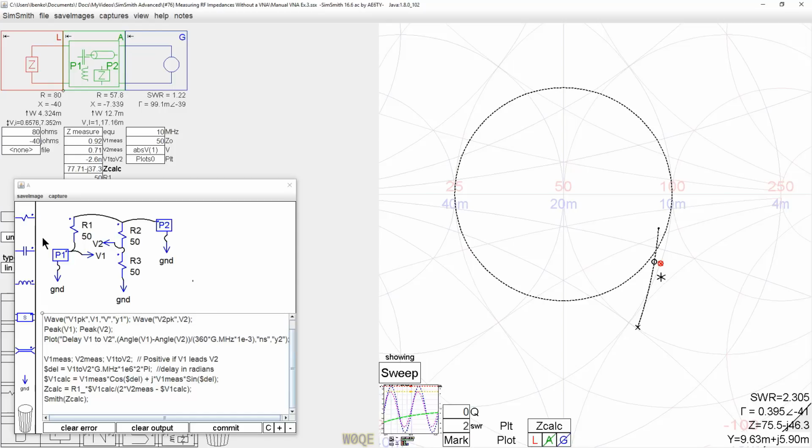And that's the kind of stuff you need to do sometimes at 160 meters where you have a lot of broadcast interference. A lot of little VNAs use a broadband power detector inside, and some use a receiver. The ones that have a double DDS synthesizer in them, a lot of times will offset the receive frequency coming back to be 5 kilohertz or 10 kilohertz away from the signal that went out. That gives you some improvement in terms of being able to make a measurement in the presence of strong, slightly out of band signals. But nevertheless, you get to a point where you can't make the measurement anymore, and the only thing you can possibly do at that point in time is up the power.